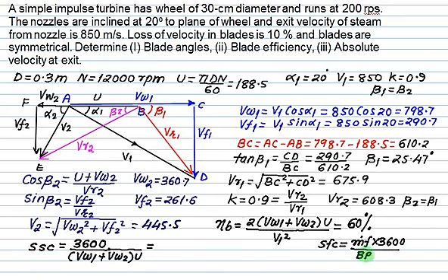In specific steam consumption we are using 3600, and brake power divided by mass flow rate is a specific quantity, that is the specific work done. So this equals W net. But remember, the unit of this quantity is kg per kilowatt hour. So there is a conversion required here, that this value should be divided by what? 1000, so that it will come in kilowatts. So 16.47 kg per kilowatt hour.